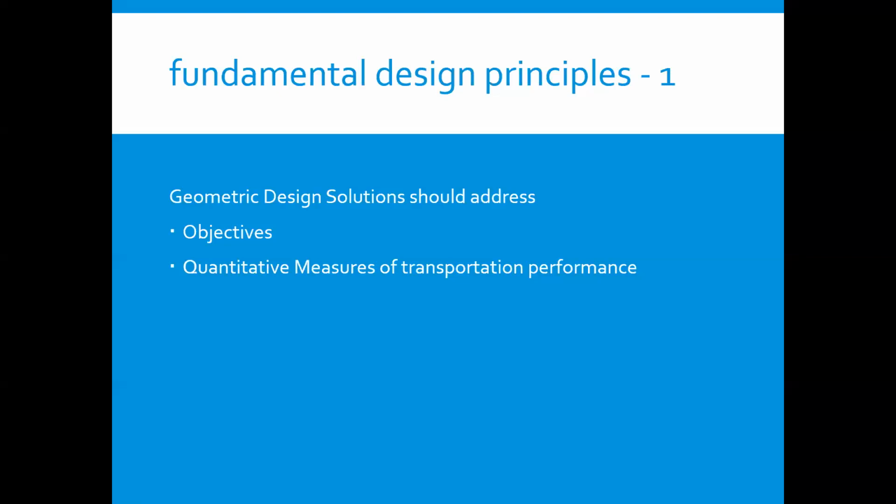The design process must transition to one that directs the optimization of a solution in performance-based terms within the context of the resources allocated to the road project. This may be viewed as a cost-effectiveness approach, but an important consideration is that the resource allocation should be considered in a life cycle sense. In other words, the design process should directly consider not only the initial capital cost of the project, but also the long-term operational and maintenance cost of the implemented solutions developed by you.